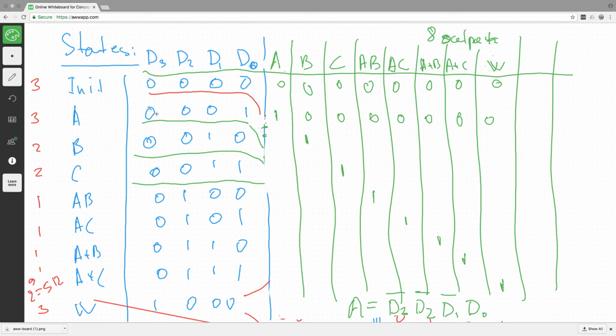That is the encoding for state A, and we want that output A gets engaged only if the finite state machine is in that state. So that will be the function to be implemented in the output encoder for output A. Similar function we can introduce for B, for C, for D, and each one will have just a single bit, just a single term. That's it.